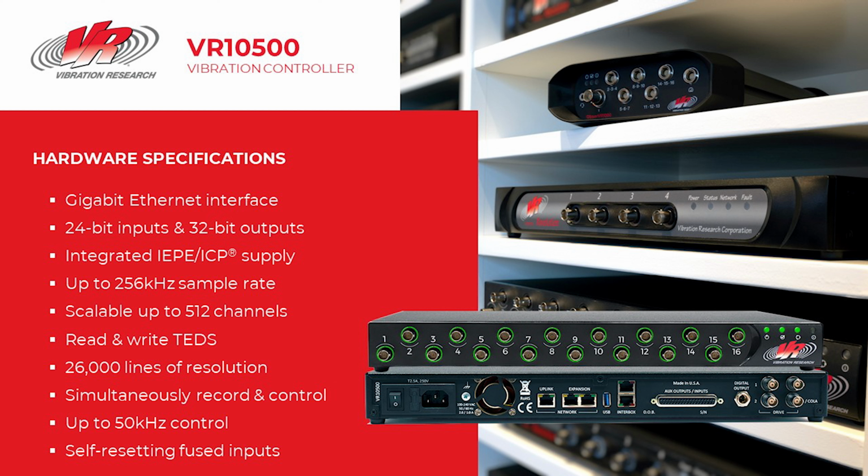The other color is yellow. Yellow is a color that means it's getting close to the saturation point of the sensor that you have hooked up. And red means that it is either saturated 100% of the signal, or maybe it also has a signal that it is not able to get any feedback on anymore. So maybe the accelerometer cable is broken, or maybe the BNC has been taken off the front of the 10500 or 9500 as well.